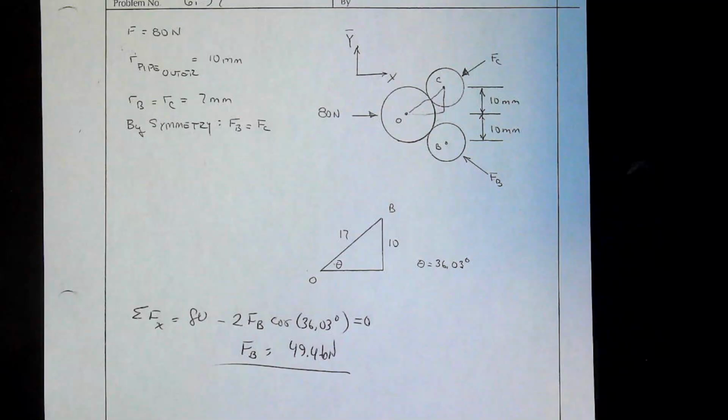So in this problem, I start from what I know. Well, I know this is 125 kilograms, since I know its weight. And so I know stuff here, and I'm going to use that to go back in through the machine. So it's the same approach to solving it. I'll just note that real quick here. All right, so here's the basic picture. I've just taken the engine out and replaced it with its weight, 125 times 9.81. And so what I'm going to do is remove this bar and make a free body diagram.